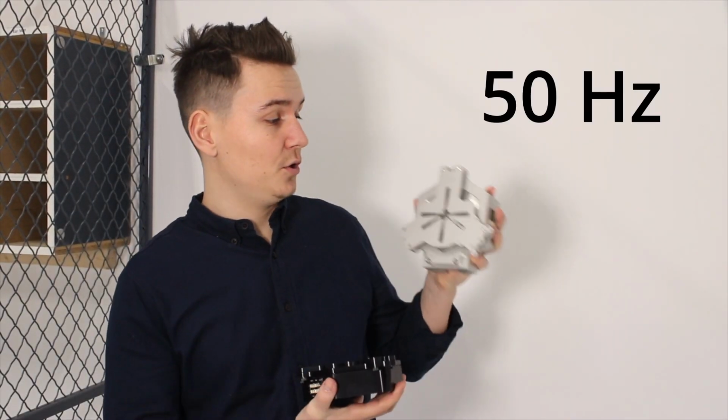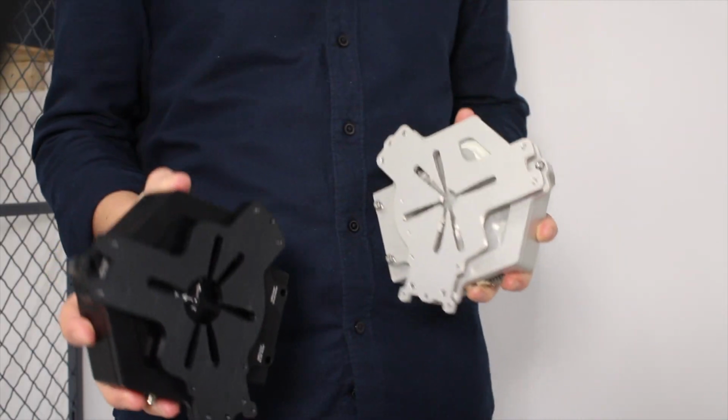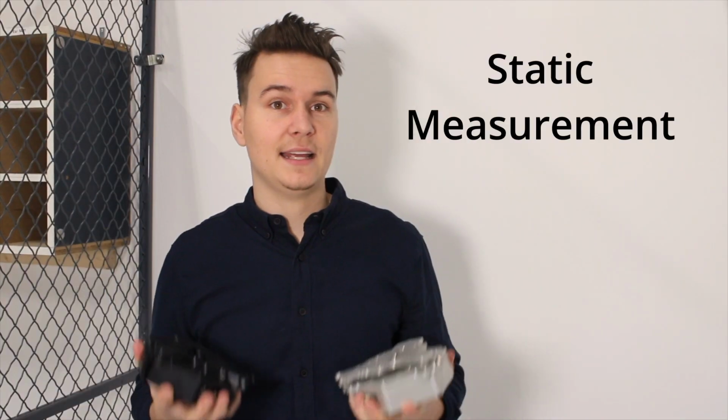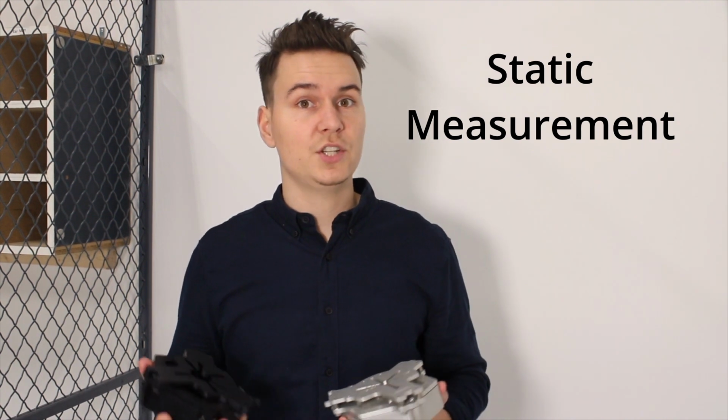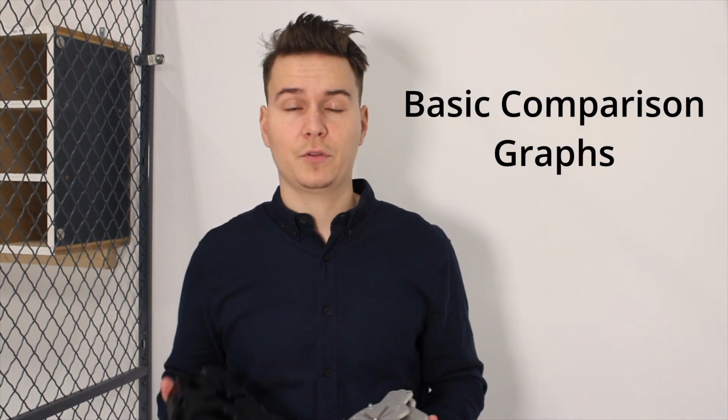The first difference is in the sampling rate, with 50 Hz for the standard version and 1000 Hz with the pro version. You can accomplish a lot with a 50 Hz sampling rate, like static measurement of thrust, torque, voltage, and current. For example, you can create basic comparison graphs of throttle versus thrust or RPM versus torque.